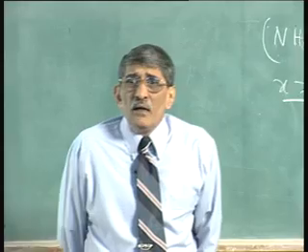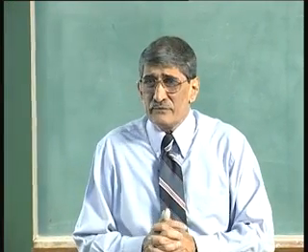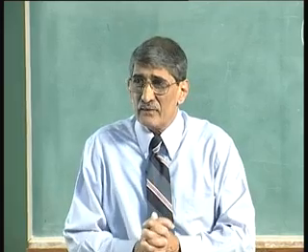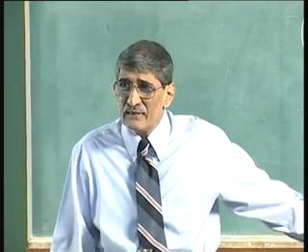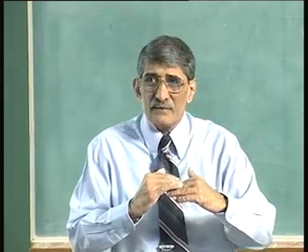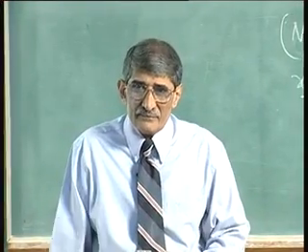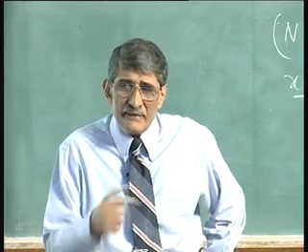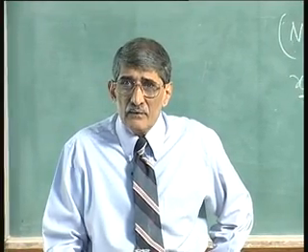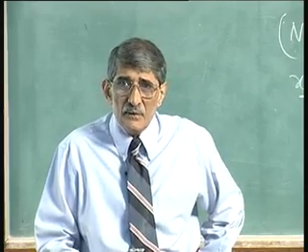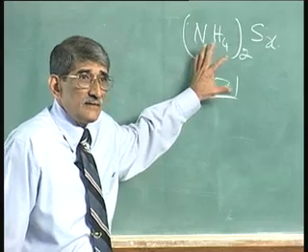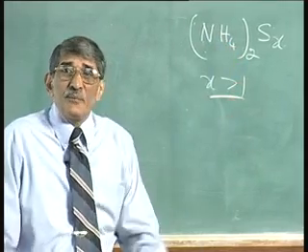Okay. This was fairly good, but even then the stability problems appeared, because this is a thin layer that is put there, covering the gallium arsenide layer. You need further protection. In fact, this is where we did a lot of work at IIT in the microelectronics laboratory as part of one PhD program, where extensive studies of ammonium sulphide treatment were done, and deposited PECVD nitride.